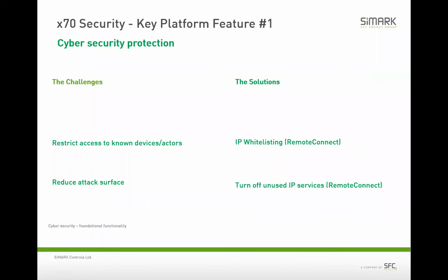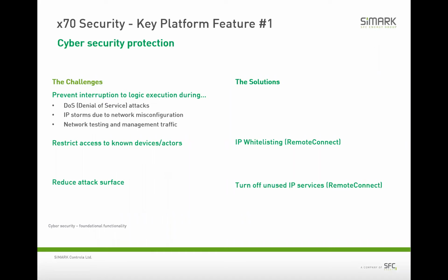The first of which was improving cybersecurity protection. One of the challenges that we find is that you need to make sure that the logic execution of the RTU will continue unaffected if it's under attack through the Ethernet port. So having designed the hardware, we set about testing that using something called an Achilles test platform, making sure that the RTU is resilient to attack through the Ethernet port like that.